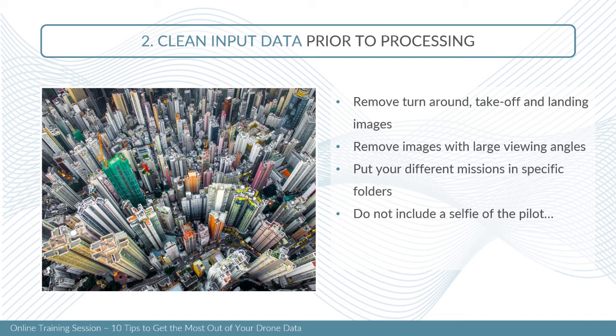You should really consider that for processing, you need to keep only what is necessary for photogrammetric processing. So what consists of your parallel flight lines with the camera top down, and remove everything that is not related to this. So don't expect the software to do the cleanup for you. The software is a photogrammetric processing software. It expects to have images that will meet the specification of a photogrammetry project. So you need to do the cleanup yourself before creating a project and importing your images. So bottom line, include only what is necessary for photogrammetric processing.